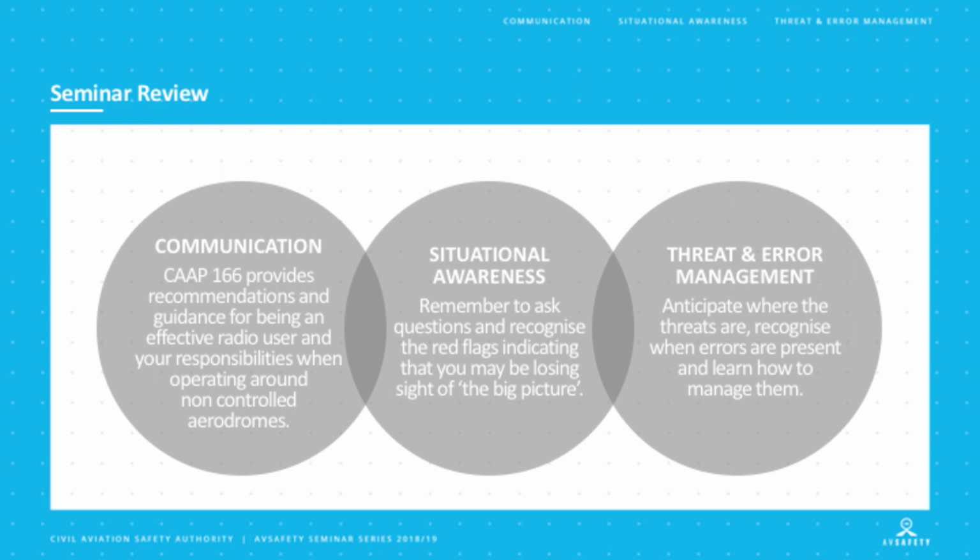That communication needs to use standard phraseology wherever practicable. Of course, use plain language if you have to, but for all intents and purposes, that standard phraseology is very important. Think what we are about to transmit, think about the audience that we are transmitting to. Am I likely to increase people's situational awareness or detract from it? And we have the greatest chance of spotting other aircraft in the CTAF environment if we use appropriate radio calls combined with a disciplined lookout and a scan for other traffic using our eyesight.